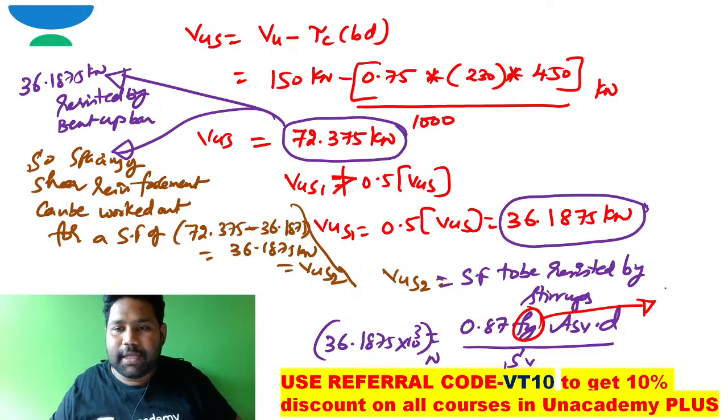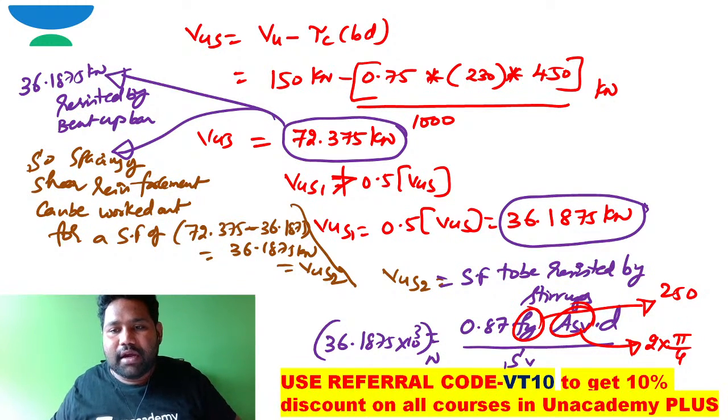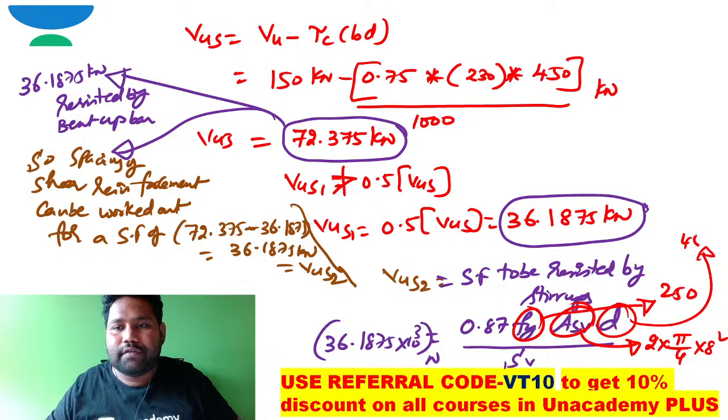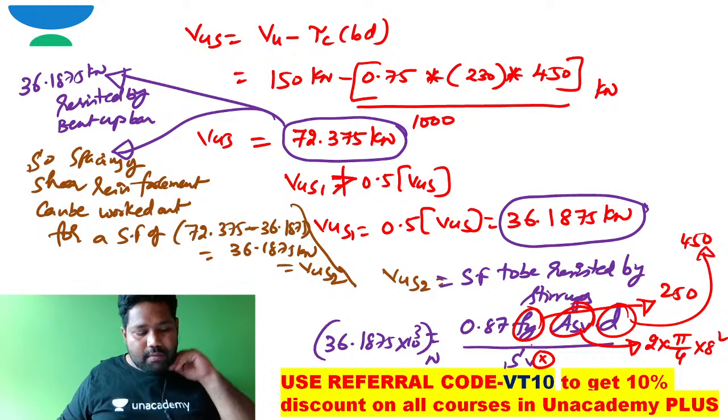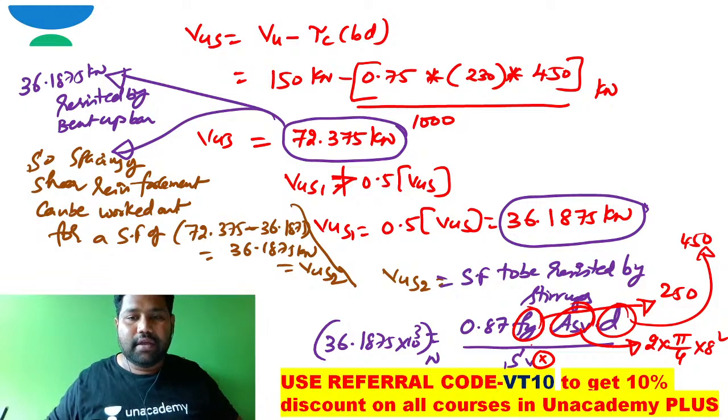So this is 250. And coming to ASV, what is this ASV? Two legged stirrups of 8 millimeter diameter: 2 into pi by 4 into 8 square. Coming to effective depth, what is this effective depth? It is 4. So the one and only unknown is SV. From this one, we are able to fix this value of SV, right?